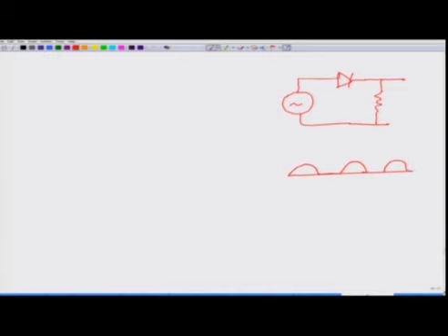This is half wave rectification. What are we plotting here? We are plotting voltage and time. Which voltage am I plotting? This voltage which appears between these 2 points, where I had put a galvanometer in place of this resistance, and that voltage drove that galvanometer and we saw the deflection. So, this is the voltage that we are plotting. This is our half wave rectification, current goes only in one direction.